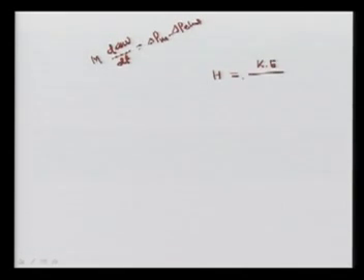You know that this M d omega, change in omega over dt, equals the change in P mechanical minus P electrical. These are the changes I can write. Again we are writing this M omega. Now this H term is called the inertia constant H, and the unit is second. It is defined as the kinetic energy stored in the machine divided by the rating of the machine, I can say PR, the rating of the machine.